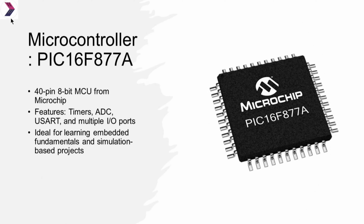The microcontroller that is used is the PIC16F877A, which is a 40-pin, 8-bit microcontroller from the Microchip company. Here are some of the features of the controller: it consists of timers, an analog to digital converter, UART and multiple IO ports. This PIC controller consists of 5 ports, which we will see in the next slide. This processor is ideal for learning embedded fundamentals and simulation based projects.